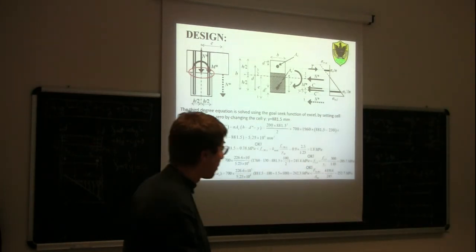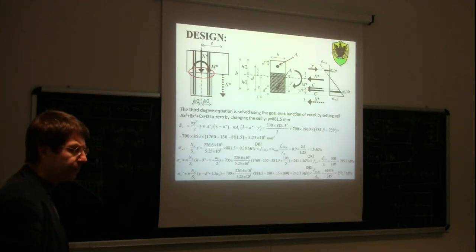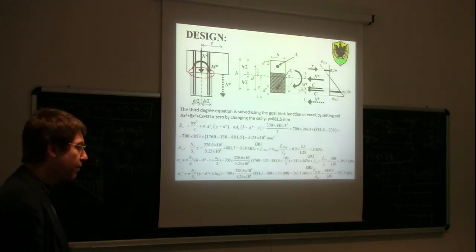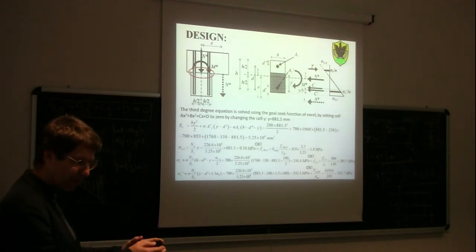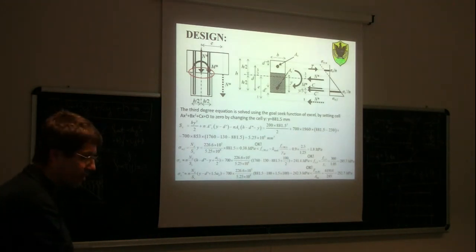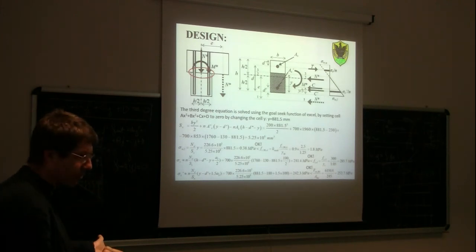The column. Yes? Where? Because of the buckling. Okay, but just forgetting about this problem of secondary stresses, if you look only here, at these 3 checks, so if I ask you, would it be the wood, the steel of the compressed rods, or the steel of the tensile rods? What would be the answer? The steel of the compressed rods, exactly.